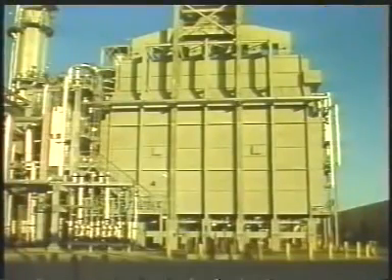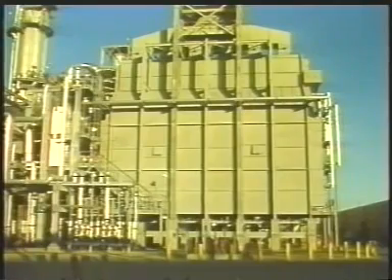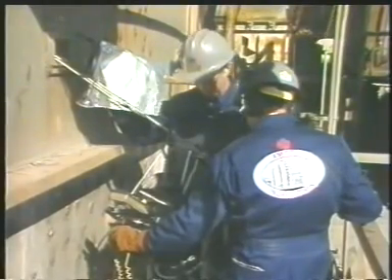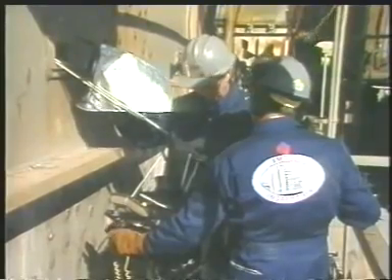A hot spot in a furnace is an area that has become overheated due to an improper distribution of heat or flame impingement. Hot spots may occur on the tubes, the refractory, or even on the outside skin of the furnace. They're a problem because they compromise the strength of a metal and cause coke deposits. Some hot spots can be detected with the human eye as a glowing red spot on the metal. In other instances, special heat-sensing instruments such as a pyrometer or an infrared scanner are used to detect hot spots.